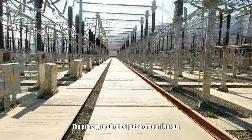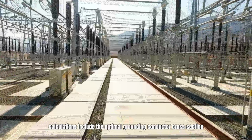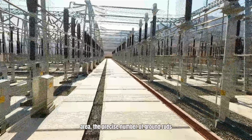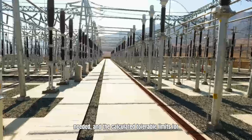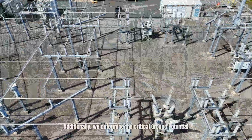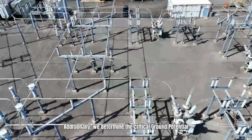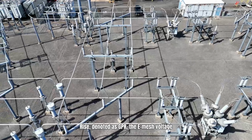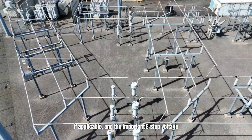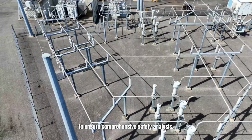The primary required outputs from our rigorous calculations include the optimal grounding conductor cross-section area, the precise number of ground rods needed, and the calculated tolerable limits for both step and touch voltages. Additionally, we determine the critical ground potential rise, denoted as GPR, the E-mesh voltage if applicable, and the important E-step voltage to ensure comprehensive safety analysis.